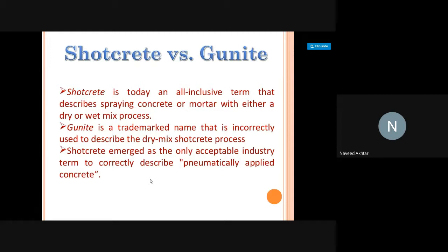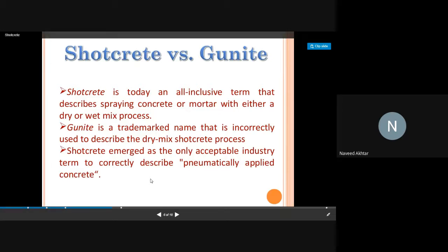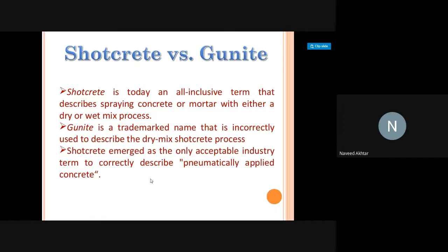To avoid landslides, these techniques are used on the rock surface. The mesh is laid over the rock and then concrete is applied. Also, when you are doing tunneling work, this technique can be used. The shotcrete technique is used, and through a gun or by spraying, the concrete is placed.